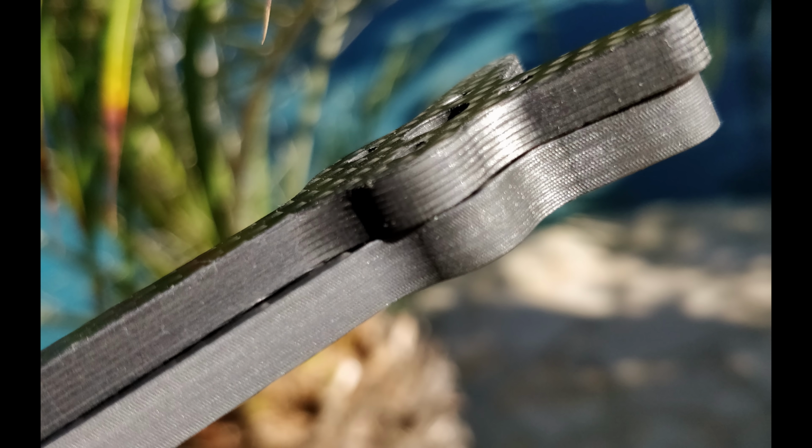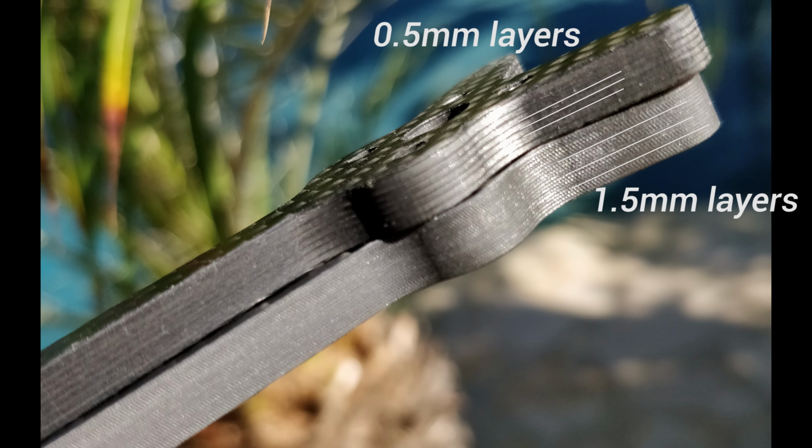Okay, but one last question before we get to yours. It's nothing that is interesting for this product, because in this case it's pretty straightforward with the pre-preg. The only downside with the pre-preg is that it's more expensive, but you get the resin there. And if you would have a laminate that were made out of layers that were 1 mm thick, I will say that that is a pretty bad laminate, because you want as thin layers as absolutely possible.